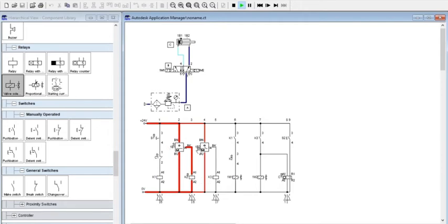The electrical flow changes to proximity switch 1B2 through input port 1 to output port 4, and it will change the contact from normally open to normally closed because of the presence of the magnetic field in this area.